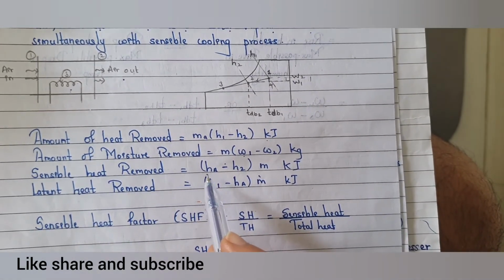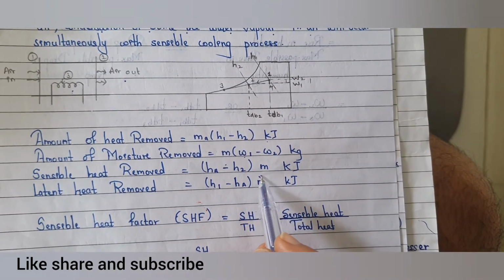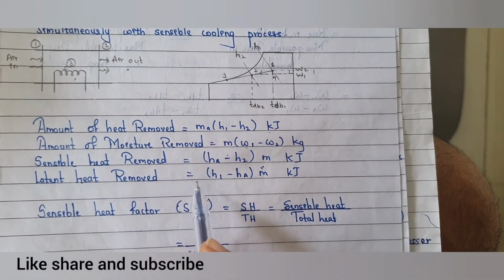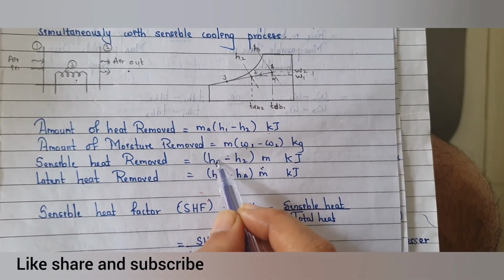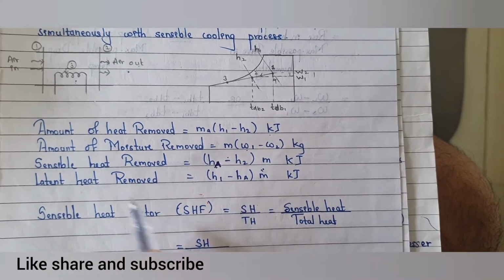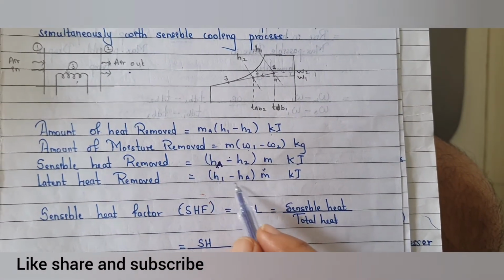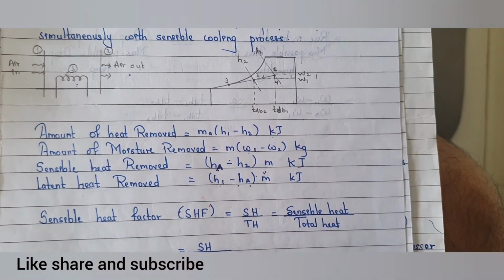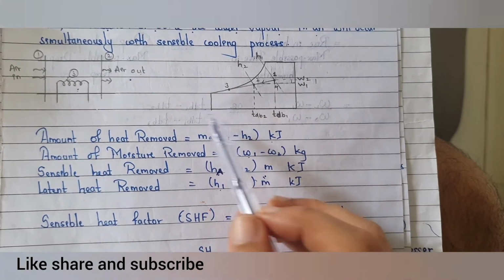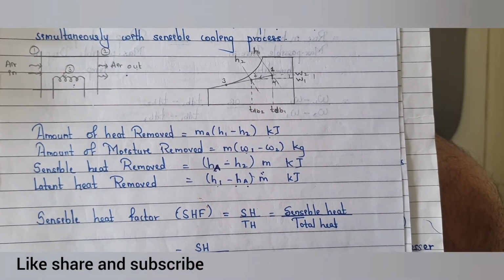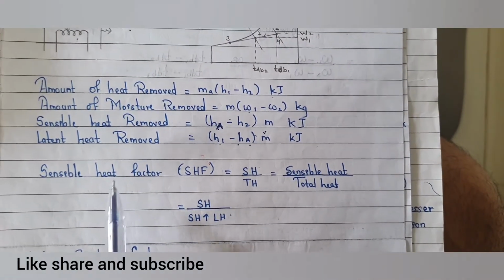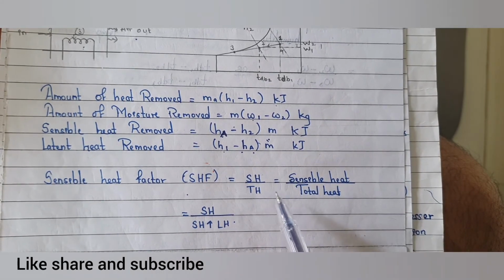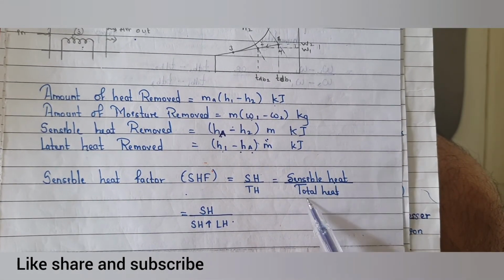Sensible heat removed is equal to H1 minus H2 into m kilojoule, and latent heat removed is equal to, actually this is not H1, it is HA, and latent heat removed is equal to H1 minus HA into m kilojoule. Here this is the graph related to cooling and dehumidification. Now sensible heat factor, that is SHF, is given by SH divided by TH, that is equal to sensible heat divided by total heat.